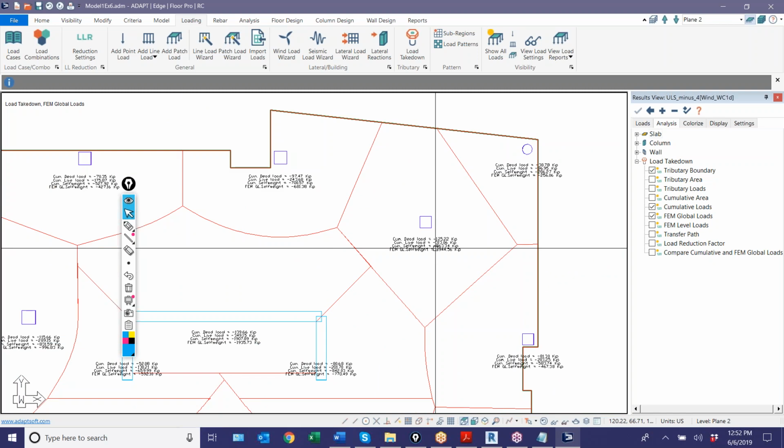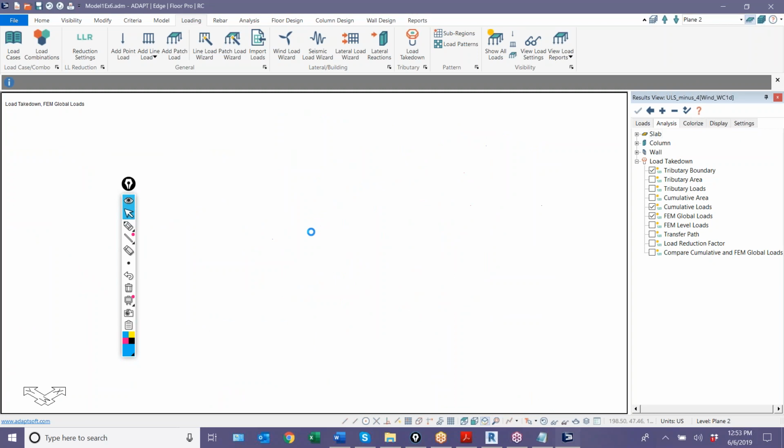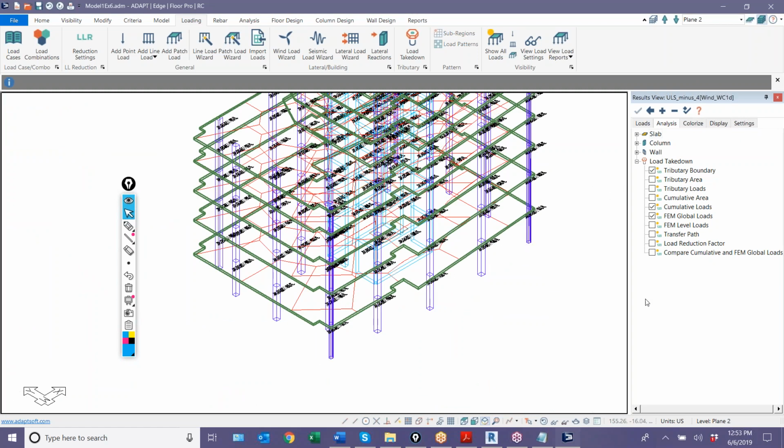The primary reason I'm showing you this is that you have two alternatives for generating the gravity axial loads for the columns, and you have the possibility of selecting either one or enveloping them when we design a component like a column. So right now we have those two buckets, those silos with data. We have a FEM solution and we have a tributary. Now it's time to design a column or a set of columns that can tap into those two buckets, if you will. So I'll go to the multi-story mode again.